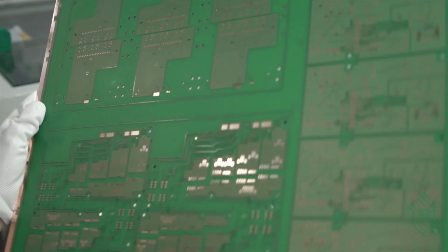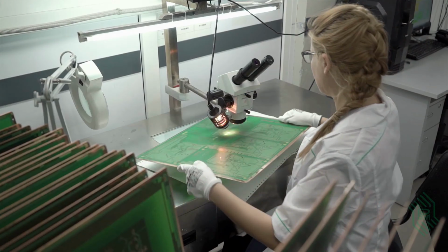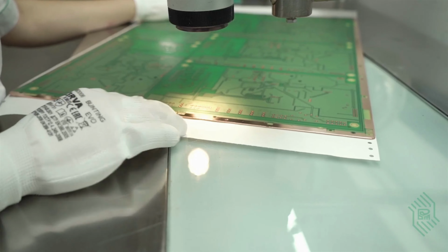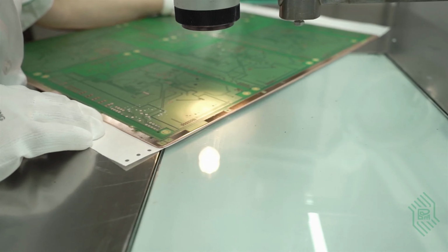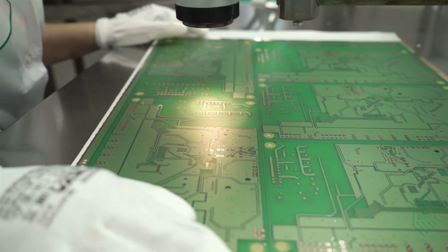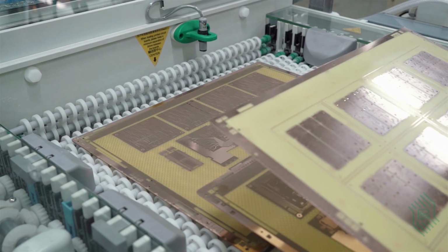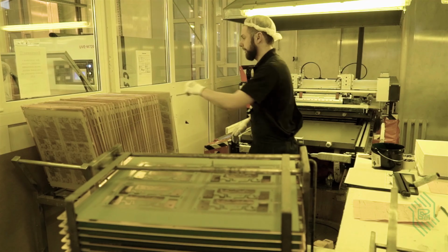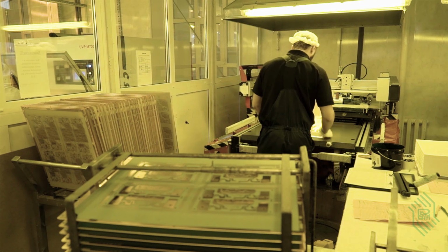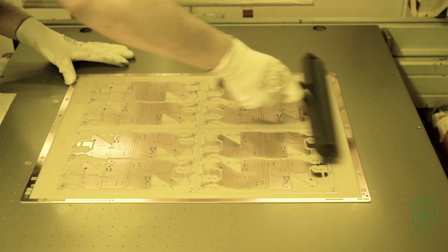In this stage, the solder mask is applied, the mask openings on soldering points are formed, and the final curing of the mask layers occurs. Before applying the mask, the copper surface is cleaned, then the necessary roughness is developed for the good adhesion of the solder mask.